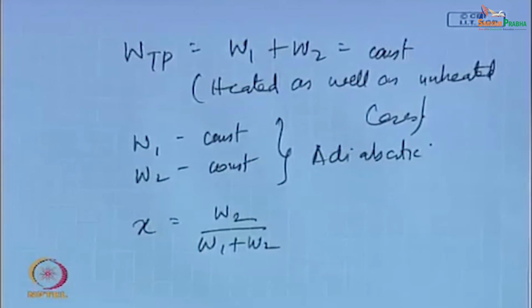In the last class we had already mentioned that if we know the heat flux, if we know the amount of subcooling of the inlet liquid, we can find out x. And in other words, if both the liquid and the vapor are in equilibrium, under those circumstances also we can find out x. So, x is definitely not a non-measurable parameter, it is a measurable quantity, or it can be derived from measurable quantities, unlike alpha.